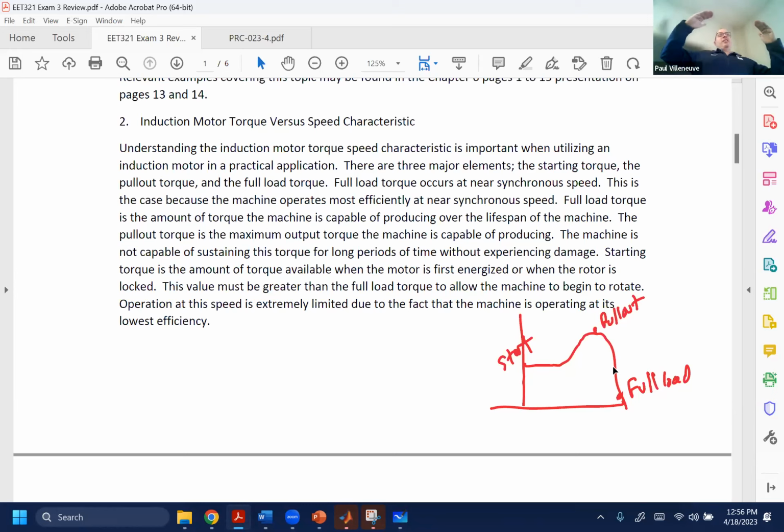Yeah, usually it basically adjusts things sometimes to 1,000th of an inch, and it can move things up or down. And the idea is that if the shafts for your mechanical equipment and your motor aren't lined up, even off by a degree, you can get something that wants to go this way and this one wants to go that way. You can put a lot of demand on both pieces of equipment. So one of the things you do, at least for automotive, is you put in shims to make sure things line up as perfectly as possible.